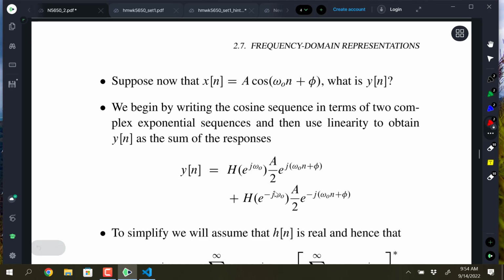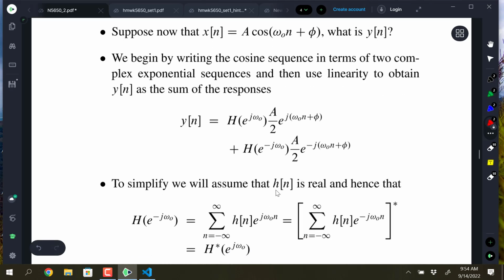And this is a really good question to ask, because as an electrical engineer, you grow up with a hands-on experiment in the lab one day or another where you have a function generator, you have a breadboard, and you put a resistor and a capacitor on it to make an RC low-pass filter, and then you connect the oscilloscope to the output, and what do you see? You see the sinusoid coming through the output, you see it's been phase shifted and amplitude attenuated, depending upon the frequency. So how does that look in DSP?